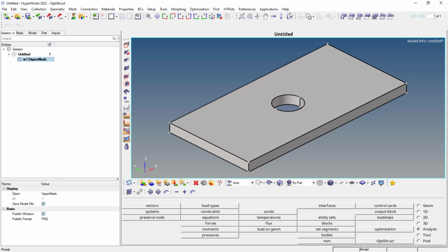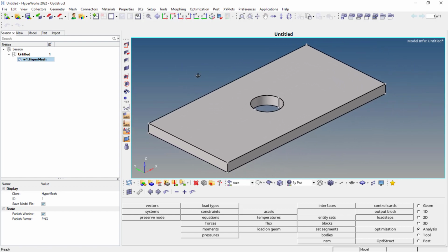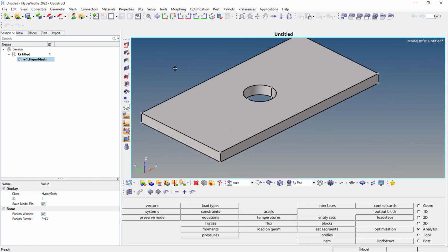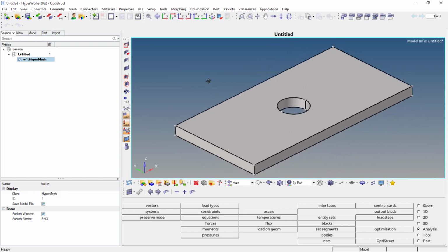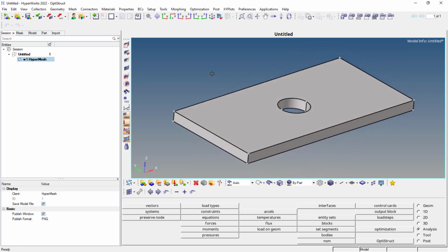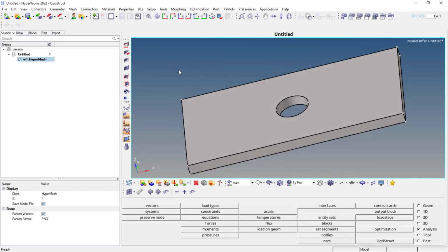Now these are the display and navigation tools. When it comes to the shortcuts, concentrate. Control and right click drag will help you to pan the component. You can drag the model along the graphics area. Again, Control, left click and hold and drag will help you to rotate your model however you want.